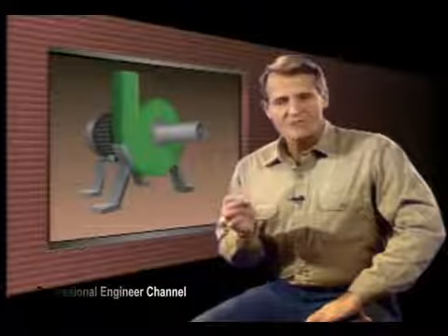Centrifugal pumps use centrifugal force to move liquids. Centrifugal force is the force that exists when an object or material moves in a circular motion. This force causes the object or material to move outward, away from the center of rotation. In a centrifugal pump, what moves outward is the process liquid.